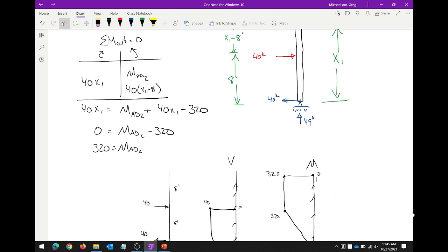It's because if you open up the steel manual, go to the NDS, go to ACI, they have these analysis aids that you as engineers can use. So if you have this case, it'll tell you that the maximum moment is WL squared over 8. And I want you to know where that came from. Well, this is WL over 2, and this is WL over 2, right? So shear diagram, up, and that's L over 2, that's WL over 2. So that area is WL squared over 8, right? That form, WL squared over 8, if you take concrete design, you use a lot, but it comes from this.